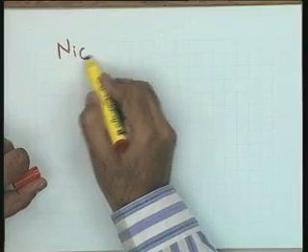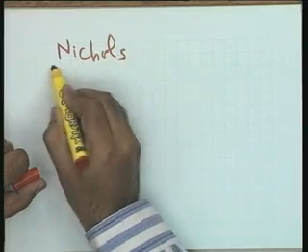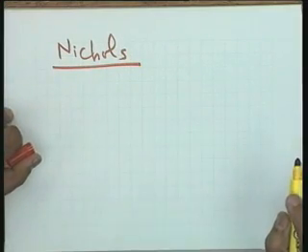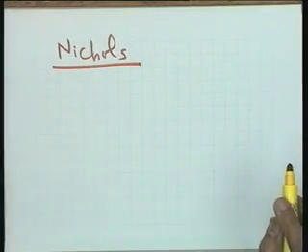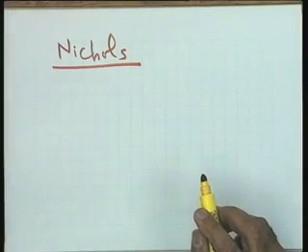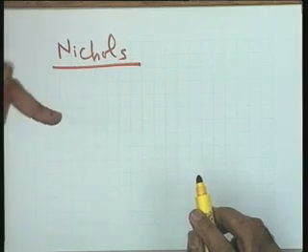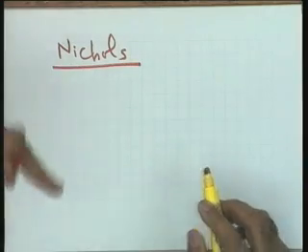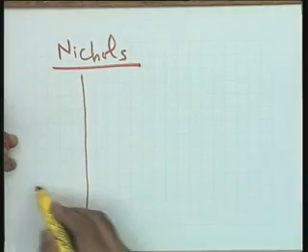Now, the last point is the following, that getting the Mr, omega r and omega b from the constant M circles is a difficult proposition. So, the answer to this problem has been given by Nichols and is extensively used. Not only the constant M circles, the problem is plotting the Nyquist plot is very difficult compared to Bode plot. So, he suggests that you make a sketch of this type.